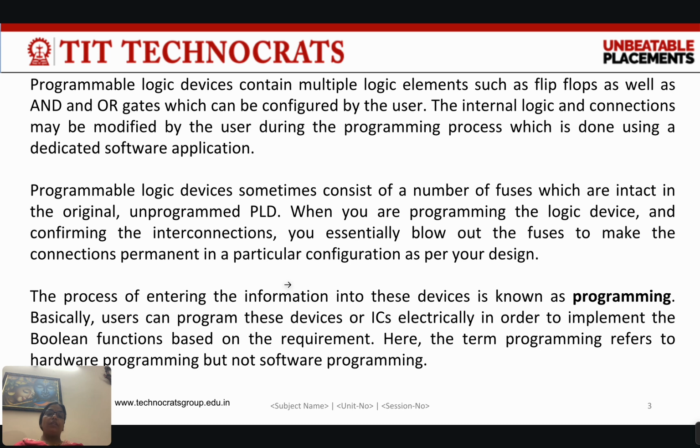When we are programming the logic device and configuring the interconnections, you essentially blow out the fuses to make the connections permanent in a particular configuration as per your design. The process of entering the information into these devices is known as programming. Basically, users can program these devices or ICs electrically in order to implement the Boolean functions based on the requirement.